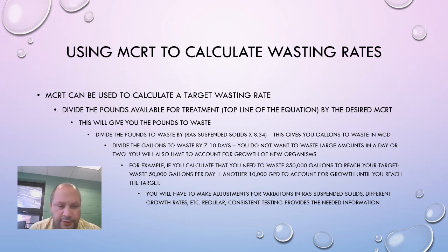So what do we actually use MCRT for? These types of questions you're not going to see in your homework, and you're probably not going to see on a class 1 wastewater exam. But I wanted to give you a little bit of information on how to practically use this in operating a plant. And the way that we would use this here is that we would pick a target MCRT. So let's say that we wanted an MCRT of around 10 days.